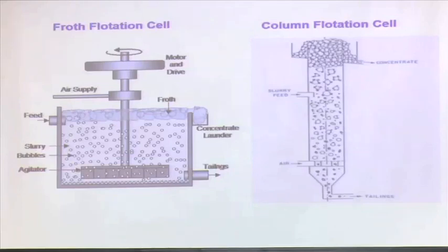Okay. So, then what will happen? The degree of hydrophobicity goes up, and then you can recover them more selectively. That is what we call collectors. The froth, as I said, needs some stability. I have to have some time to take them out, even for mechanical operations. So, sometimes the froth may not be stable because it has to withstand the atmospheric pressure also. So, there we add some chemicals again to make the froth stable, that is called the frothers.